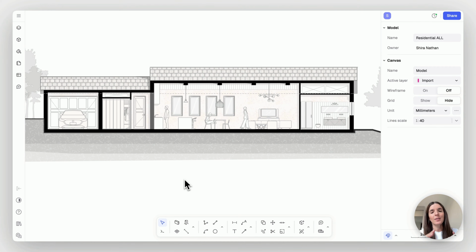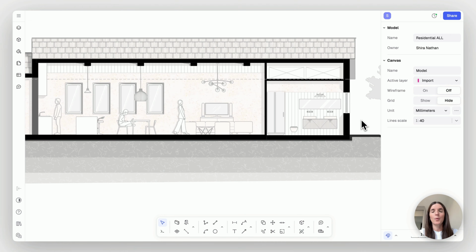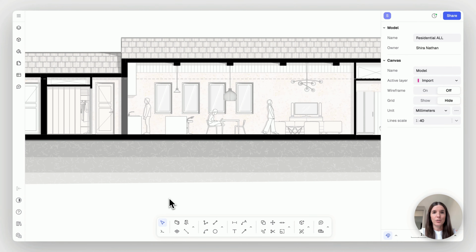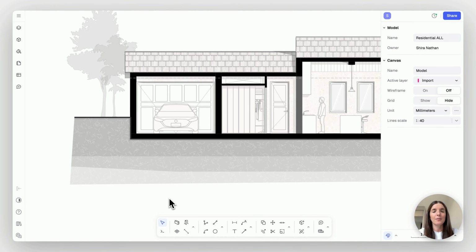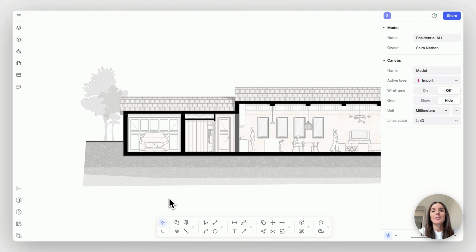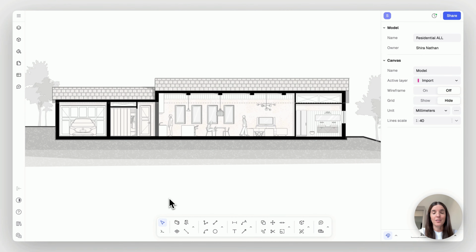I want to talk now about how you can portray the details of construction and materiality. For now, we've used pretty straightforward, simple, bold walls, for example, so just black. But as you may know, walls tend to have different layering on them. So it's called sandwich walls, and when you're detailing the construction of a building, you really want to show what the wall is made out of, gypsum, isolation, and other. And this depends on the scale you're going to portray your section on. So in the end of the tutorial, we're also going to talk about presenting this and exporting to scale.